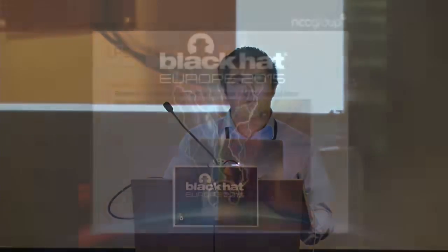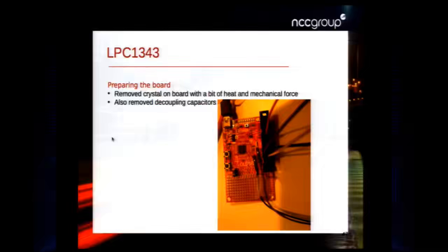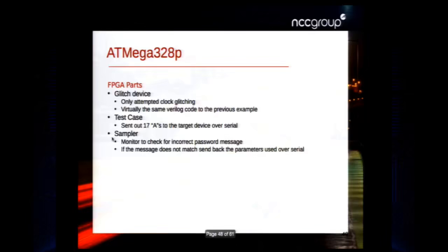So moving on, when I prepared the board, I ended up removing the crystal on the board with a bit of heat and some mechanical force. And I also removed the decoupling capacitors, as you can see right here, kind of. Once again, this is what I used. Oh, that's mistitled actually.